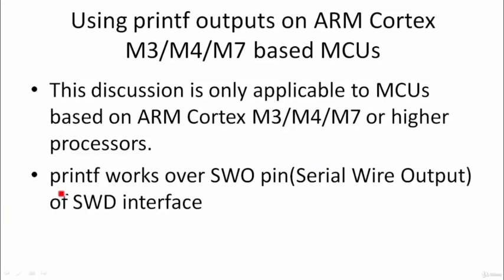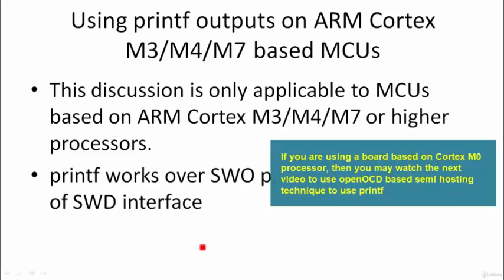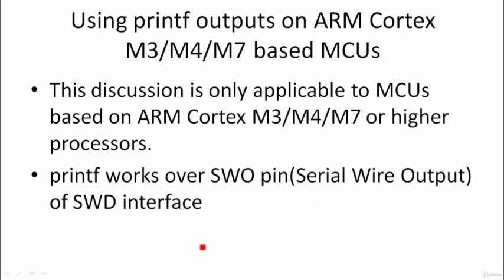This discussion is only applicable to microcontrollers based on ARM Cortex M3 plus processors, M3, M4, M7 or higher. It will not be applicable to ARM Cortex M0 or M0 plus processors, because in that case you will not be able to use the ARM Cortex processor's trace functionality, which we are going to discuss in a moment.